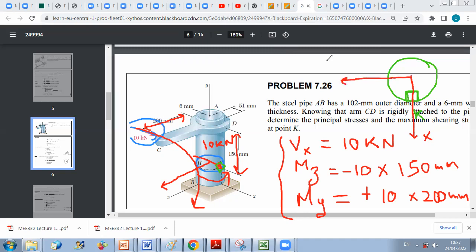You know that it's the case of plane stress. You can consider, for example, x prime, y prime for plane stress. So I will call this x prime, and according to the general convention, we rotate from x prime to y prime in the counterclockwise direction. So I will take y prime along minus z. And I want to determine the state of stress in plane x prime, y prime.